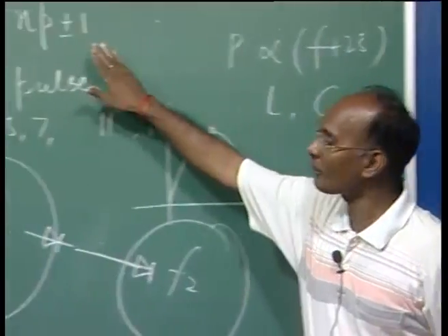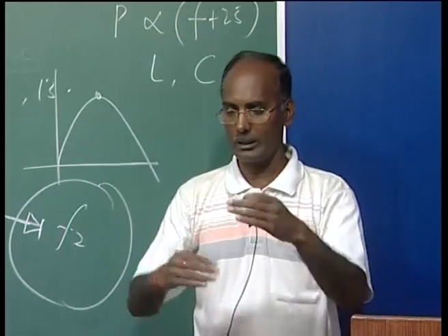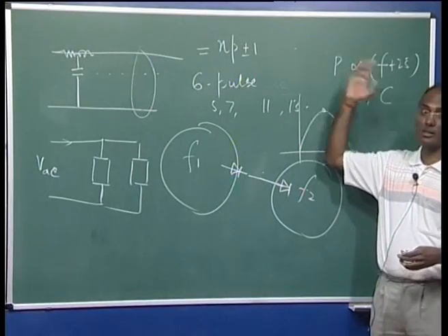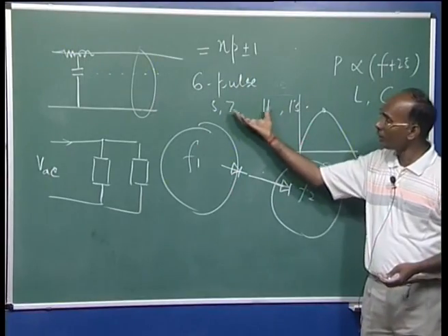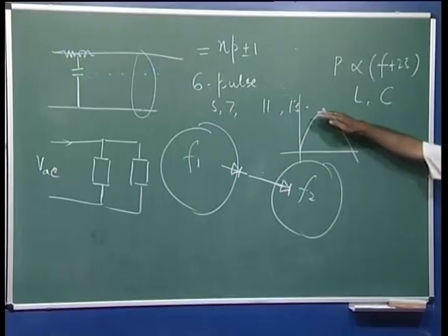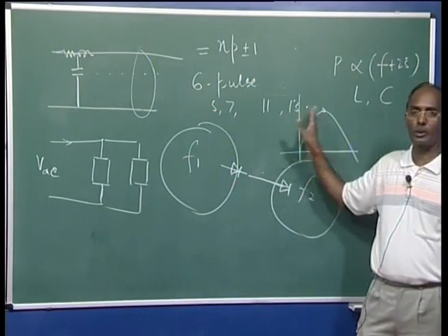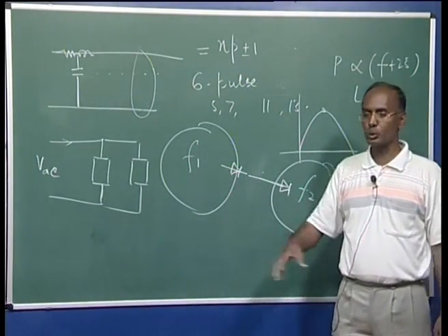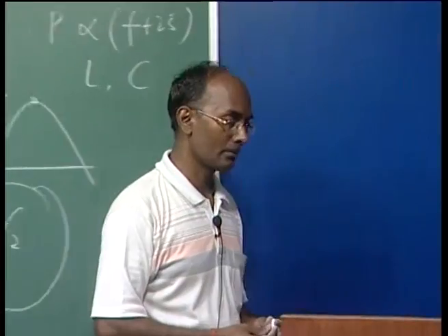Other than these, harmonics are also present in the system due to overlapping: one valve is conducting, another is going off, and it takes some time. Due to that we have some uncharacteristic harmonics, and if they are not filtered out properly, they propagate in your AC system and may create many other problems that we don't want. No doubt, for higher order harmonics the magnitude keeps decreasing, and the magnitude is highest for the lower orders. But still, if you have many devices in any area, the harmonic component injected into the system will be more if you are not using filters.